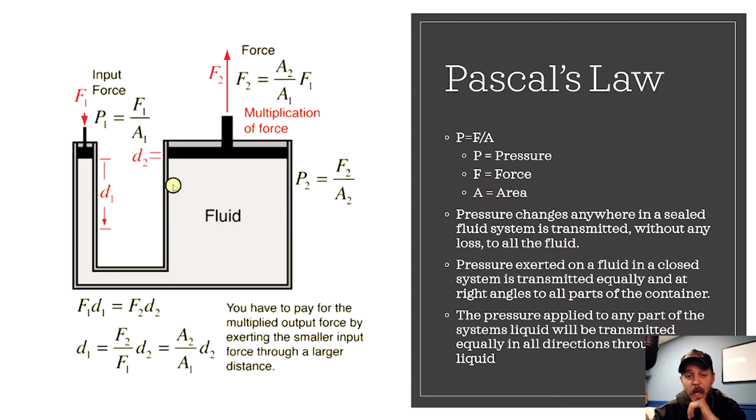So if we have a little nick, now we're shooting 100 psi worth of fluid pressure out here. That's going to reduce the overall force we're able to apply here, or we can apply it, but we may not be able to retain it because that pressure is leaking by. And if we leak by some pressure, we're going to drop down.